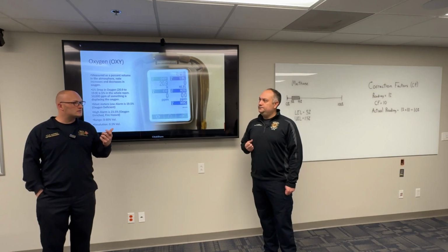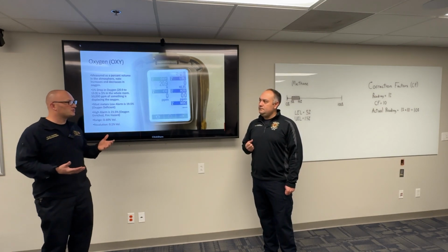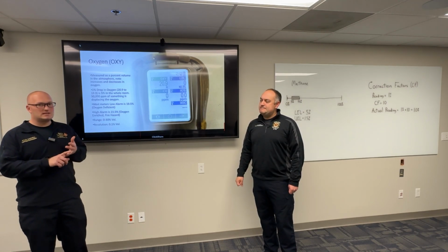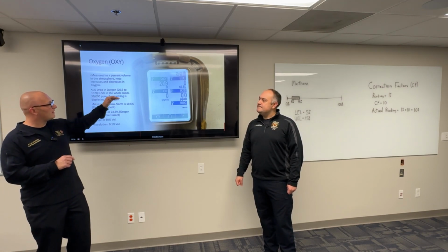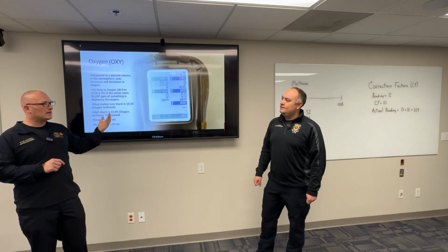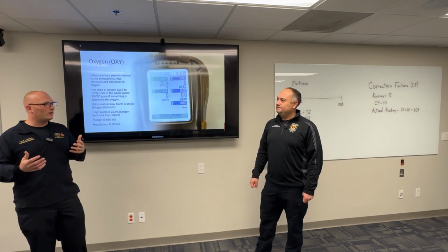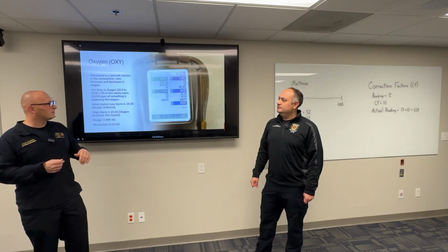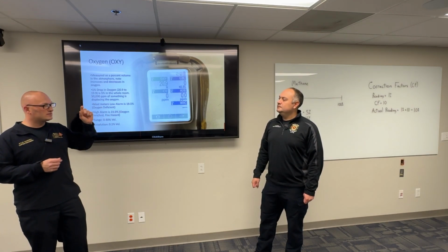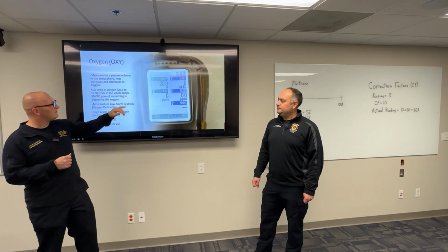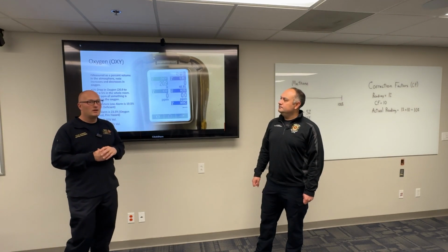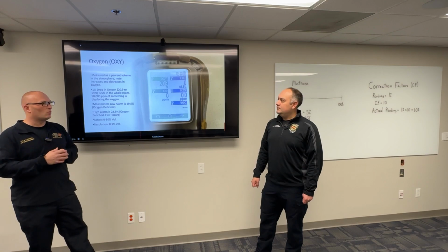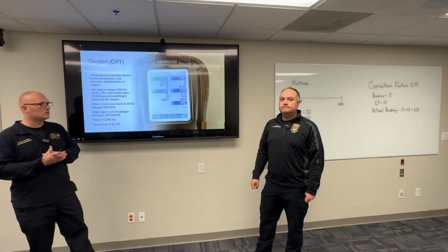I know on a lot of our calls, guys concentrate, especially on CO calls or anything with a meter, on the LEL and the CO readings. And the oxygen is always kind of like, if it's not alarming, it's not getting your attention. Kind of like the squeaky wheel gets the attention type of deal. So with this one, like Nick mentioned, that's something to keep an eye on. Always keep that in the back of your mind. If this drops below 20.9, you have something significant there that's displacing that oxygen that's worth finding and starting to look into what's going on.